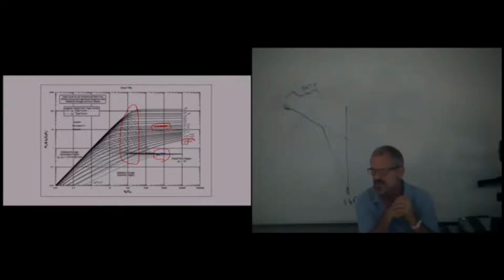So what's the degree of reliability in that case? Because we haven't seen MTR yet, and we are going to find the permeability and the other result parameters by using the type curve. If you're simultaneously fitting both the data and the derivative data, one to solid lines and one to dashed lines there, your confidence is good.